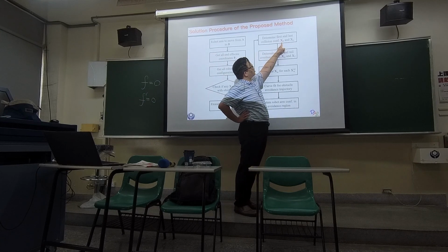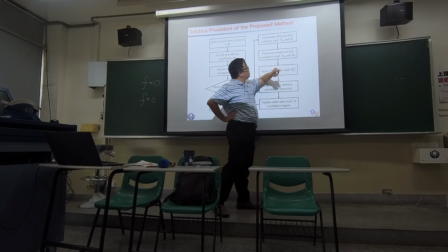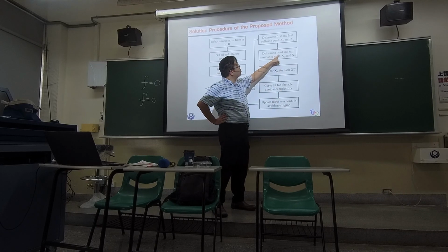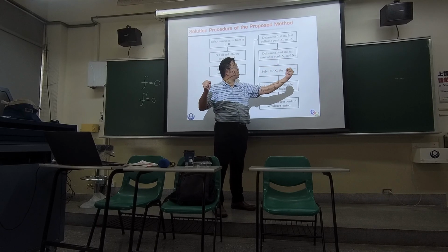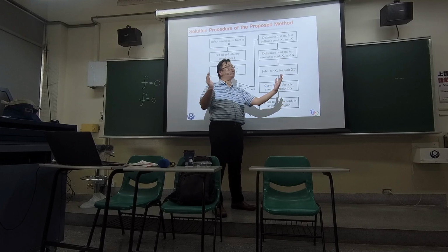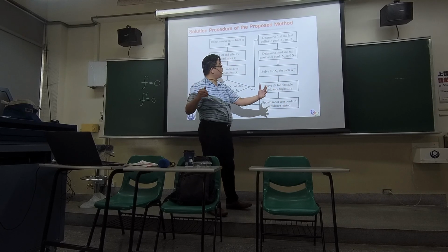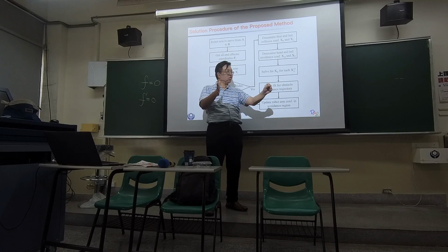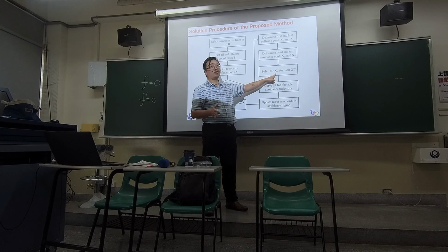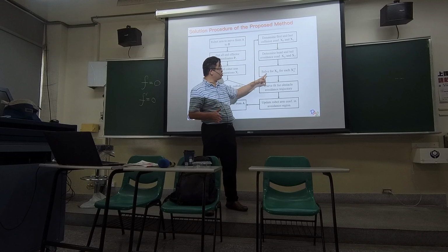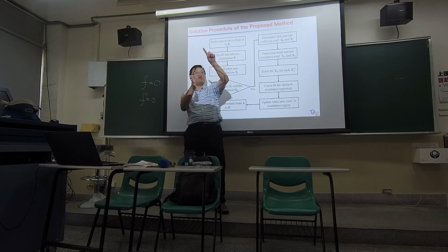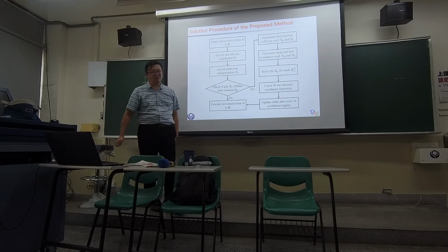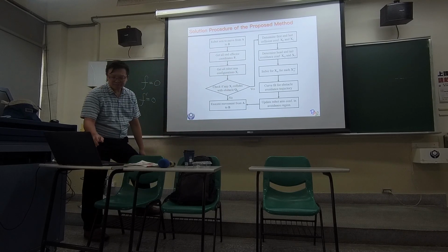Determine what is the first collision point and what is the last one. Then move wider, choose a head point and a tail point. That's where you want to do obstacle avoidance. Within this range, choose several more intermediate points. Solve the optimization that I just showed you. And then you will have new points connected. Then that's the avoiding trajectory.